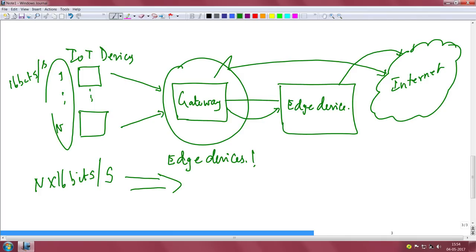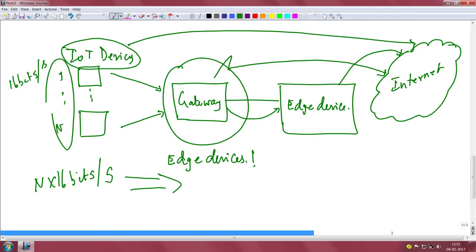One simple way is you use this gateway purely because of the fact that these IoT devices do not talk the de facto internet protocol, which is essentially TCP/IP. They talk some simple embedded code which can communicate in its minimalistic way to this gateway, and the gateway now takes the responsibility of saying, okay, you have given me data on a protocol that I understand very well, but if I have to push this data onto the internet, I have to convert this data into the de facto internet protocol standard, which is indeed TCP/IP.